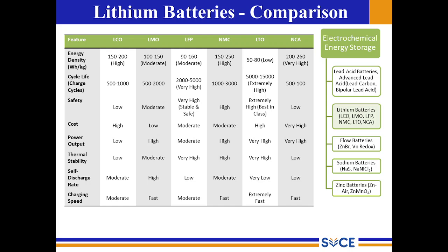Safety is best in class for LTO batteries and lowest in terms of NCA and LCO. Cost is very high for NCA and high for LTO. The other batteries are reasonably okay. Thermal stability is very high for LTO and lowest for NCA.